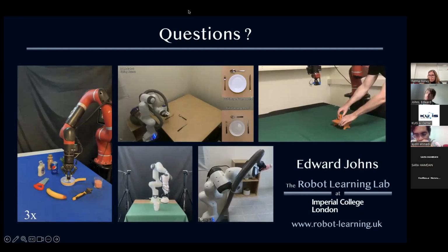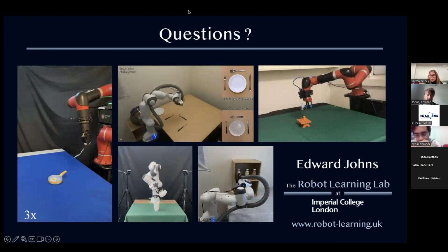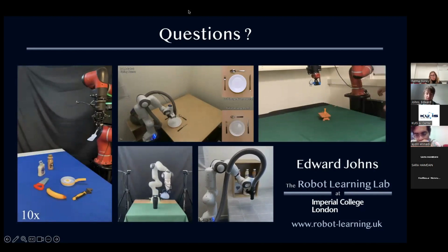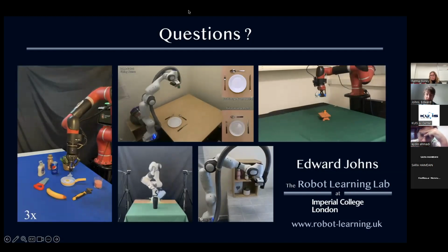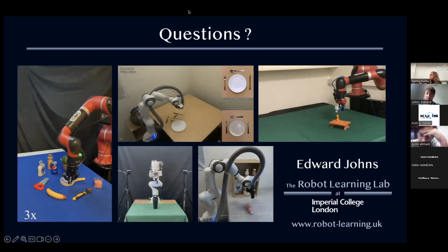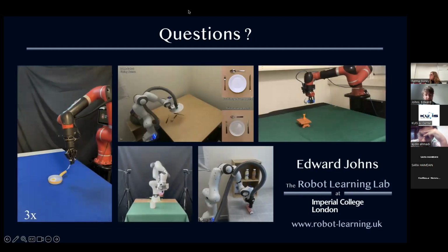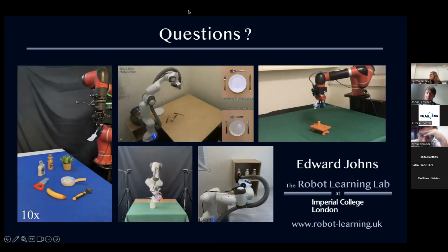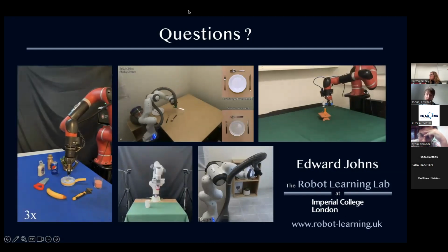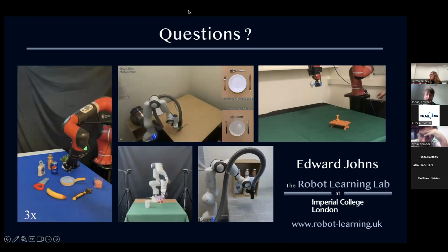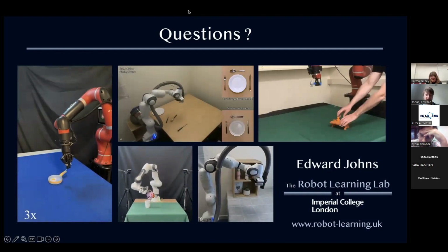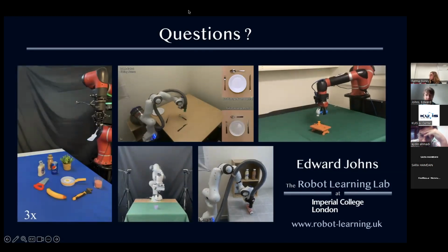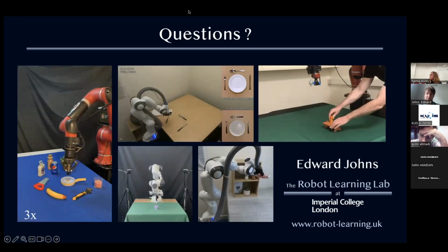Yeah, so we're doing things quite differently to how imitation learning is normally done. A traditional behavioral cloning type approach is just regular supervised learning on image-action pairs. The typical approach would be to train a robot in an end-to-end manner, where you would directly predict from image to action, and you might use something like a transformer to do that. However, that's still very inefficient, and it requires lots and lots of demonstrations. So a lot of our work is thinking about how we can do this much more efficiently.